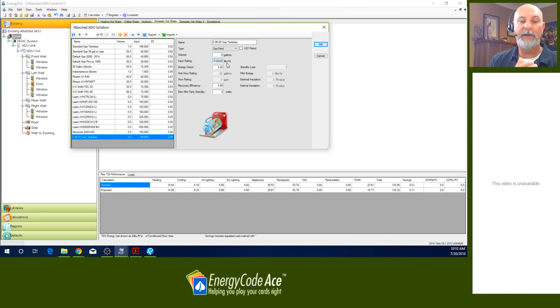But if the project is registered with a HERS provider and you go to complete the installation certificate, the installation certificate makes you put in a water heater that is within, I think, 10 or 15% of the BTU input rating. So if you put 199,900 and they actually installed one that was 150,000, technically you're going to need to update that CF1R, re-upload it to the registry so that the installer can actually register an accurate CF1R. So some of you may have run into that situation.